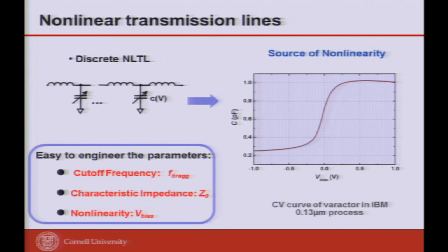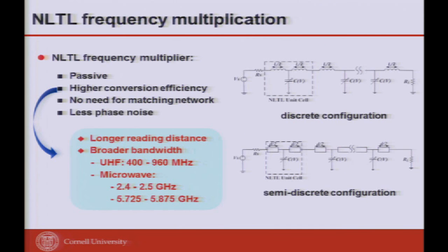So this is a nonlinear transmission line generator, and once you figure out the conversion, given the nonlinearity of the varactor you are given and the inductors you can make, you can construct the correct nonlinear transmission line for harmonic conversion purposes at the right impedance.